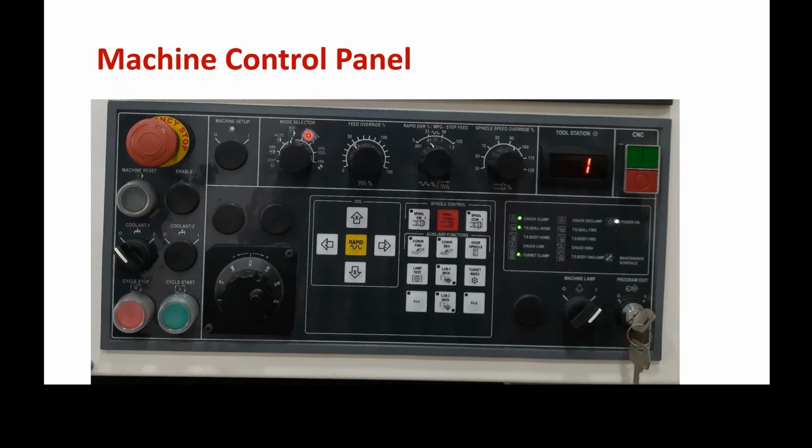Part programs are ultimately converted into electric signals, as we discussed in detail in module 1 and module 2. So instead of executing a program, if you want to move manually along X and Z, you have to go for the manual pulse generator. Manual movement along X and Z means you don't push the slides for movement.